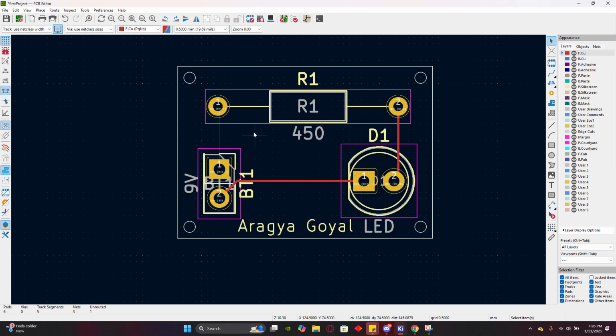You can either go onto the back copper layer, or, since this resistor takes up a big chunk of space but there are no wires going through it, you can also run tracks underneath components just to make sure they don't interfere. It'll depend on a case by case situation, but usually the easiest thing is going onto the back copper layer. But you want to organize it in such a way that you minimize how many of those lines intersect regardless.